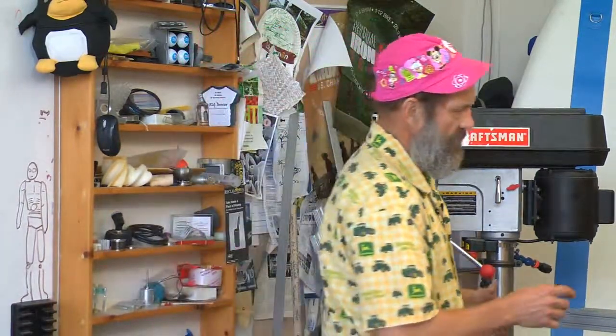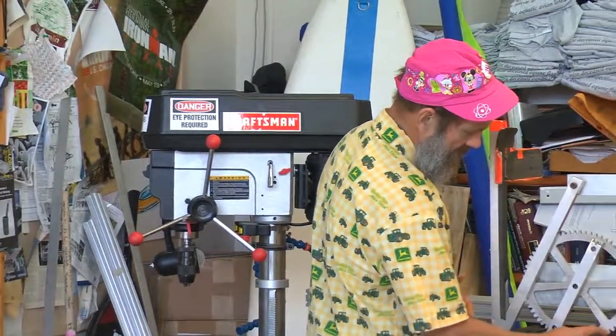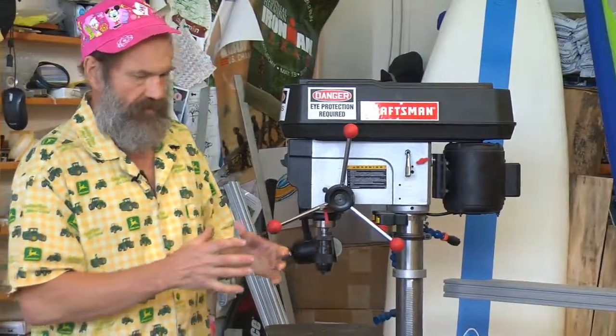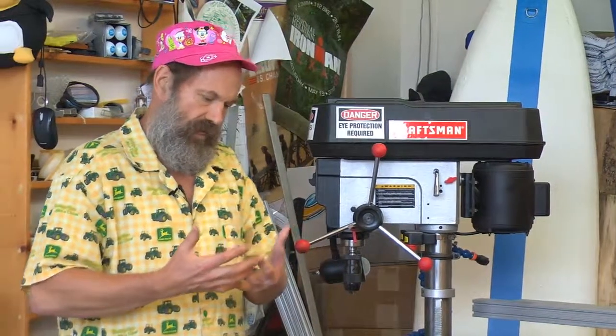It would allow you to very quickly play what if with the mod of the gear. Remember, the mod in millimeters would be telling me how many gear teeth I have around this entire circle. So when the mod gets bigger, I have a much bigger tooth and much stiffer, although then I start having higher gear tooth separation forces. I start having not as fine resolution of motion of control, but it's much stiffer. So there's always a trade-off.